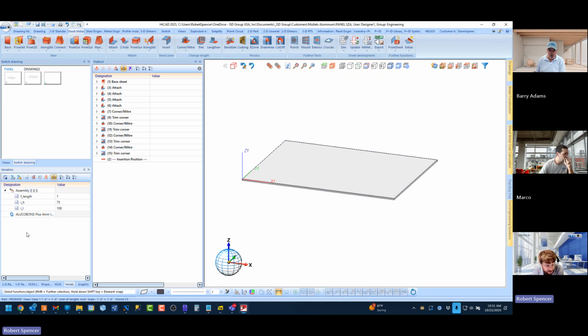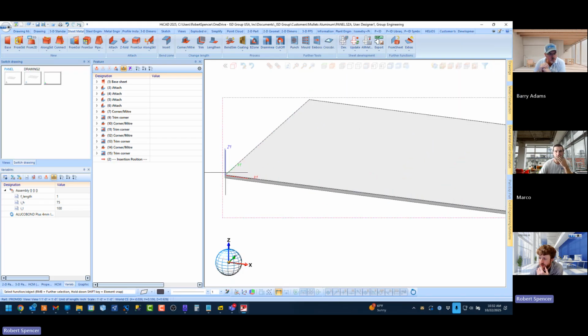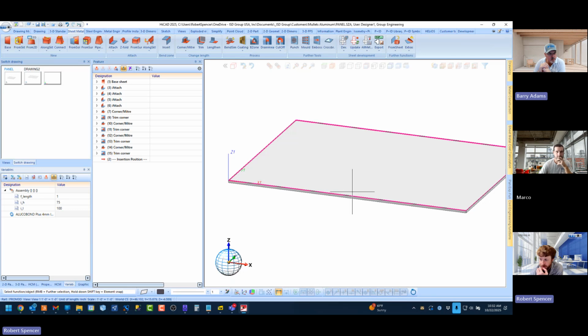Variables can be under parts only or assemblies or whatever you need. So now what this does is these are no longer just applying to a single part, they're going to apply to the entire assembly. Correct. Because let's say when we go to add maybe a stiffener behind this flange here, and we want the length to be able to parametrically adjust with the panel.